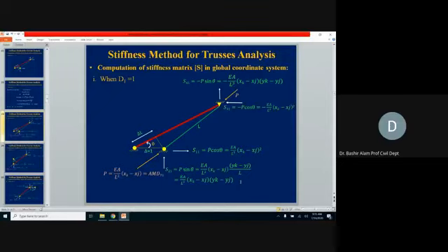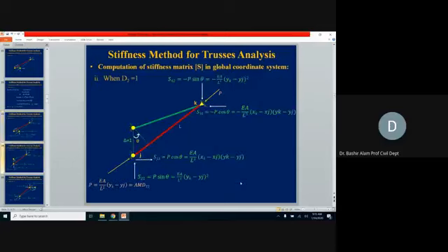We go to the next step now. D2 equal to 1 we will provide. So this is now the configuration where, corresponding to D2 in the vertical direction, we are sliding, rolling it in the upward direction. This is delta equal to 1 now. And this is angle theta, here at joint J, angle theta with the horizontal. If this is angle theta, it means this will also be angle theta.